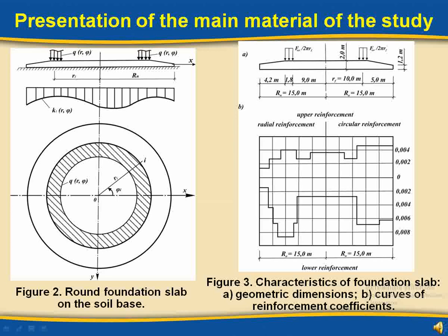The slab has a finite stiffness, but large enough to ignore membrane forces acting on the foundation bed and having little effect on the overall slab operation, especially on its load-bearing capacity. The load from these forces is perceived only by the lower part of the cross-section, so they cannot exhaust the load-bearing capacity of the slab. The behavior of a reinforced concrete foundation slab at any operation stage is described by systems of resolving equations, combining equilibrium, geometric and physical equations.